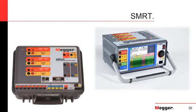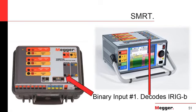Now, why is it good for the end-to-end testing that we're talking about now? Because we have a built-in IRIG-B decoder in binary input number 1, which can be used with either an external GPS device or to decode the IRIG-B signal that is running in many substations. So it's, I would say, a very good tool. In terms of the equipment itself, I'm not going to praise the beauties of the equipment and whatnot.